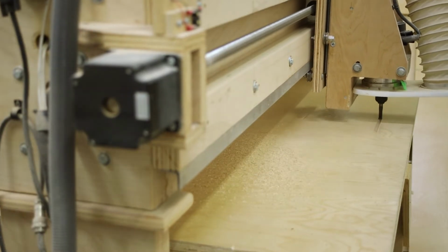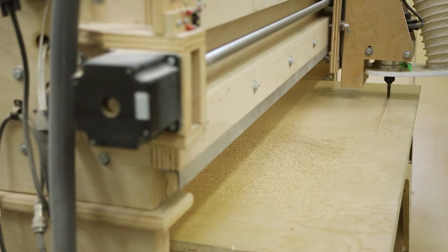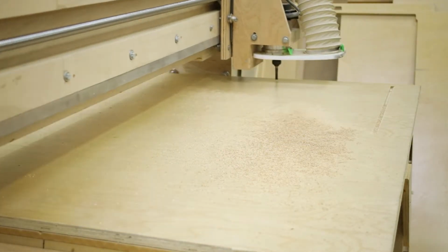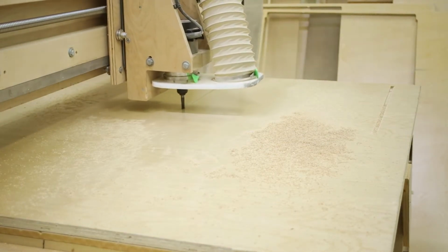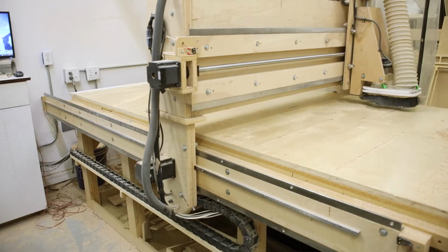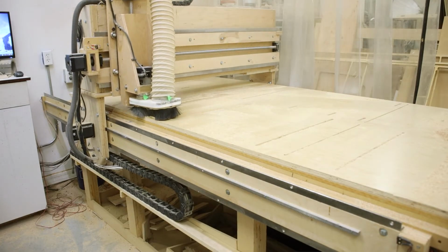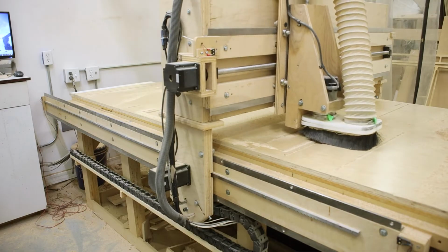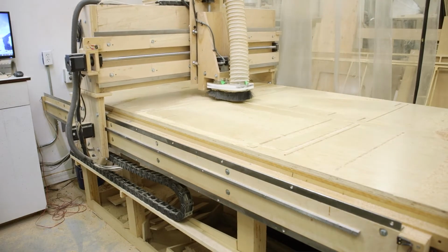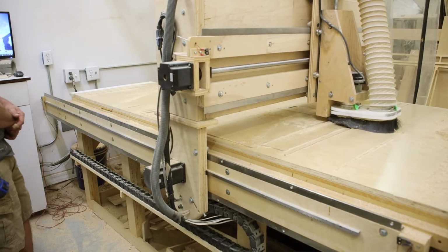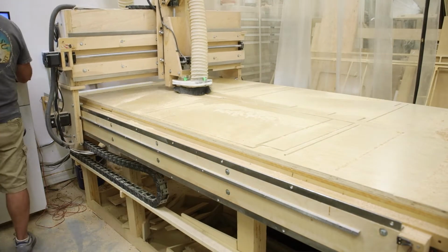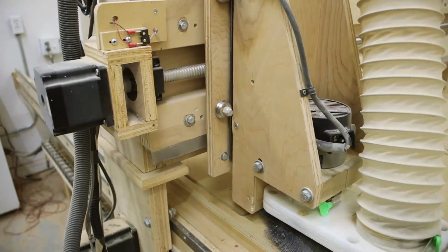And this is what dado cutting looks like without the dust boot, which is really dusty. Yeah, at 4 times speed. Once the dados are cut, we go ahead and put the dust boot back on. Make our rough cuts first, remember, leaving 4 hundredths, and then we'll come back and finish up with a single finish pass. This at 15 times speed.